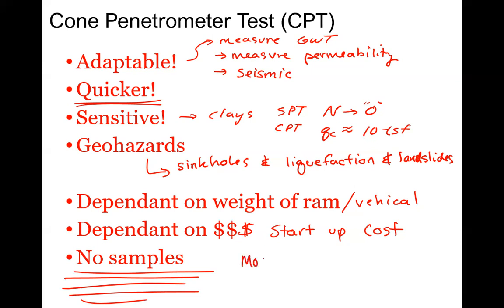So most projects you will see use both SPT and CPT, especially some of these roadway projects in Florida. They'll use SPTs to classify and get hands on a soil sample and do lab tests. But then if they encounter any really thick layers of clay, then they'll bring the CPT truck over and do a few point measurements too to get a better understanding of the clay layer. So these are two tests, CPT and SPT, you'll come across. You might also come across the rock quality designation, especially on the FE, because they like to ask that question for some reason.